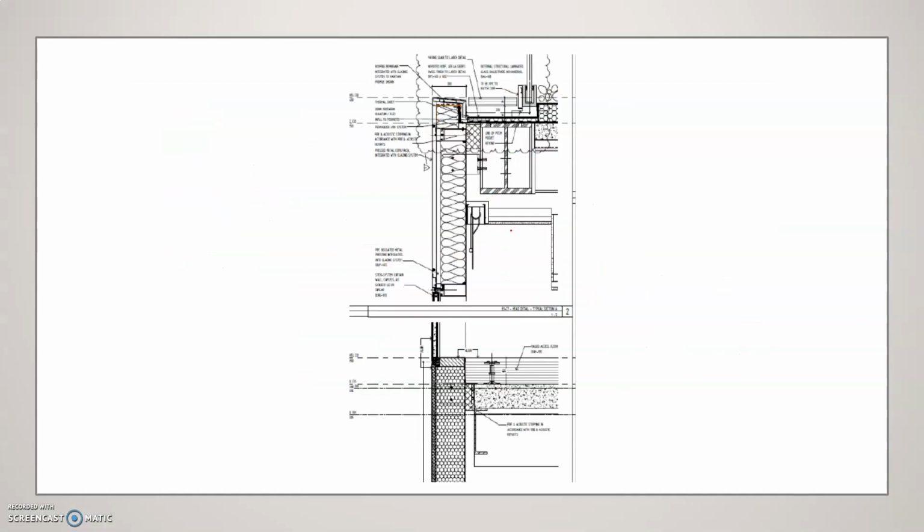On this one, again we have the balustrade detail here. We have some sort of steel section. Normally a steel section looks something like this. So this would be some sort of steel section, and then we'll have to put the glass. That could be laminated glass, and then we'll have to fill this bit with silicone. So that'll be the balustrade detail.